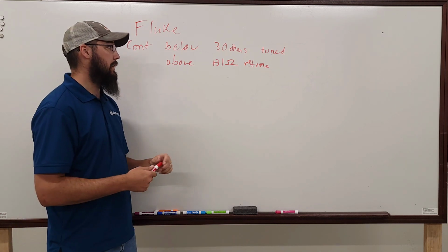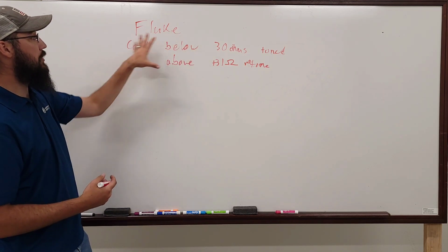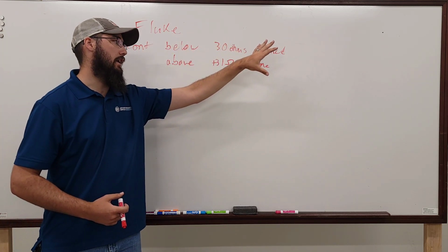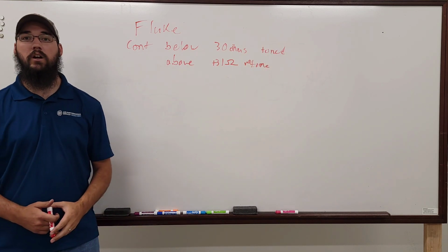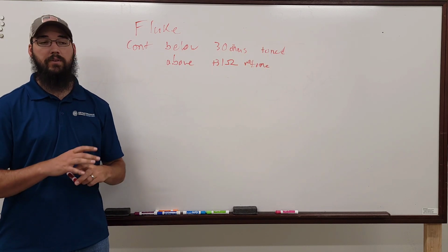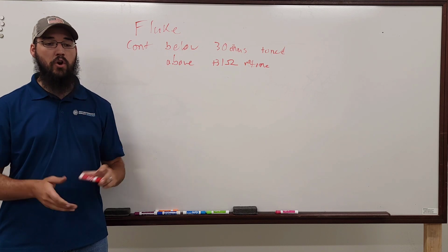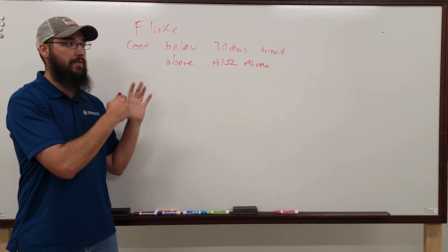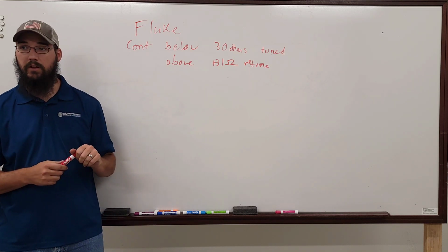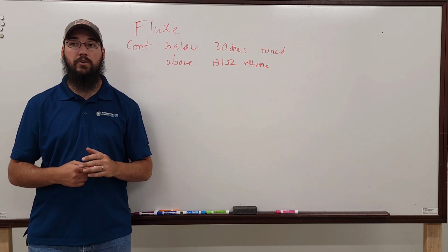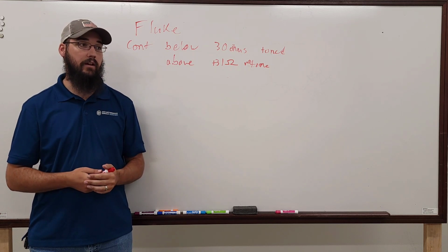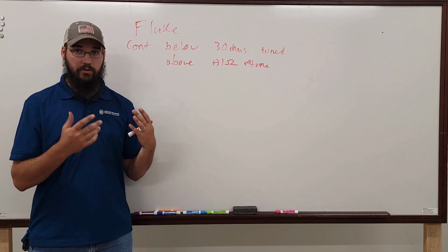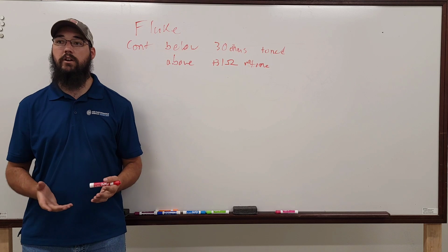Now, one of the things we have to keep in mind too, so this is continuity test. This is why, before I get on the other thing, I am so much against using continuity test for any kind of, unless you know that you're looking for a direct short, it's not the right mode or procedure to be using. Right, so there are applications where continuity is effective, okay? If you know that something is shorted and you're trying to find that short, it is a great method because you already know you've got a direct short to ground.